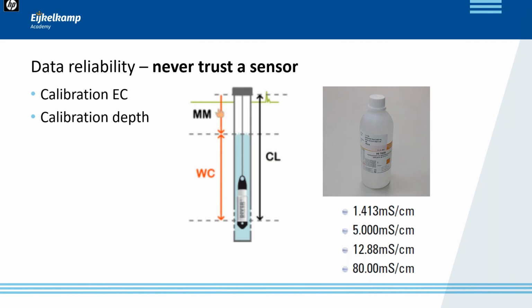In order to obtain consistent results, every water quality sensor needs calibration. It is a very important part of successful water quality measurements, and this should be carried out regularly. It means for the EC sensor, checking the readings of the sensor on standards, and if needed, adjustment if the reading deviates too much from the standards. A very simple check to see if your sensor is working correctly: EC sensors should read 0 when not in the water and dry.